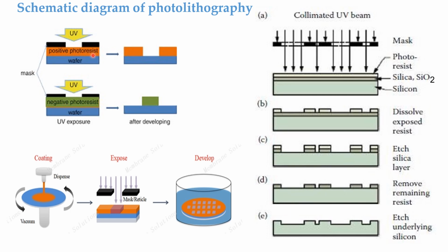In case of the positive photoresist, when UV light falls on this photoresist, we can easily dissolve it, or it gets soft. Whereas in case of the negative photoresist, if the UV light or radiation falls on it, then it becomes harder and it will stay here, and the other part we can dissolve. So then finally we can etch the silica layer to get this kind of device to make some